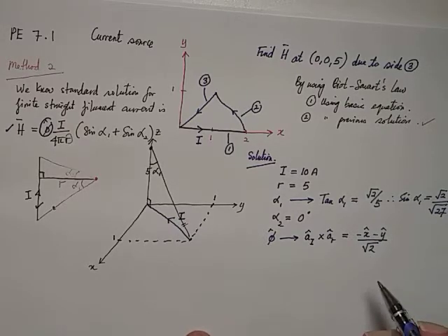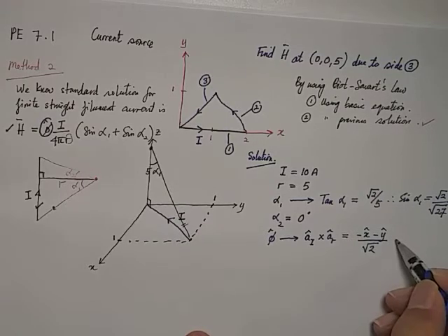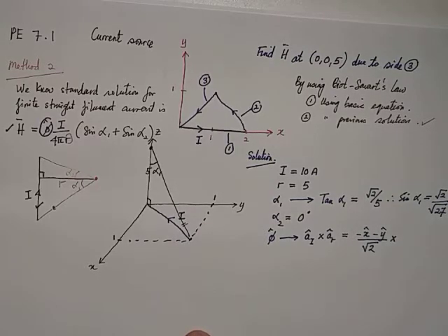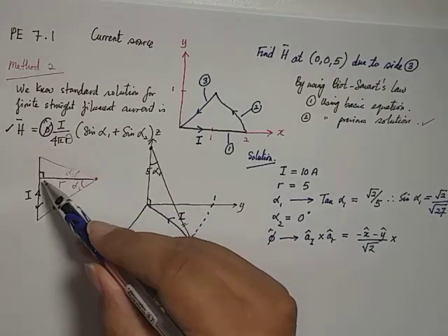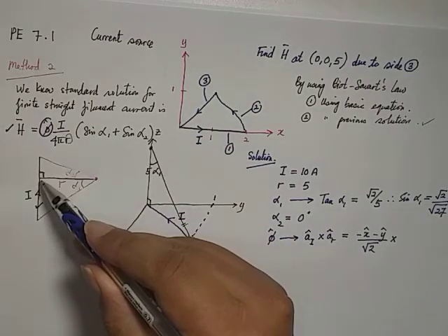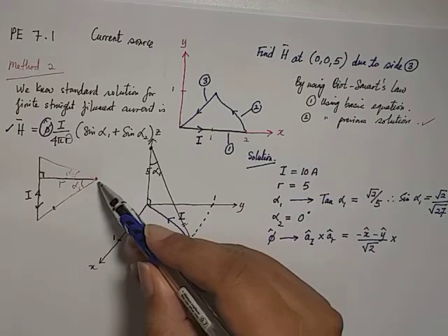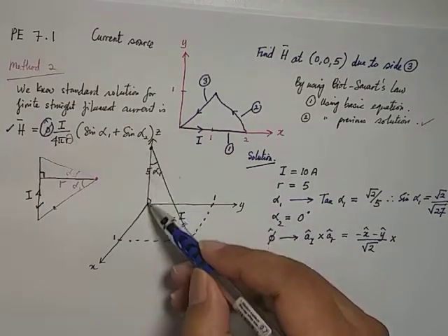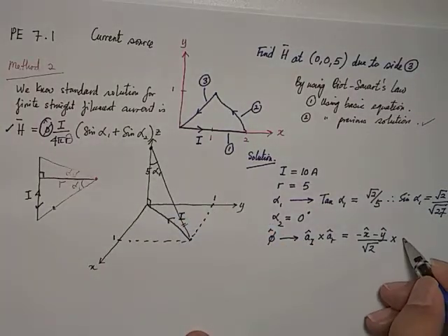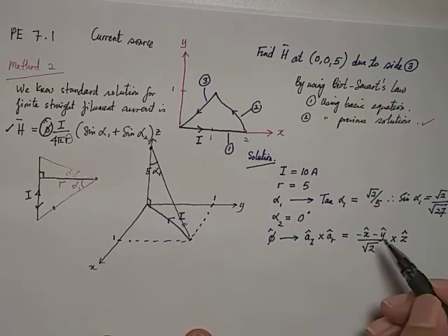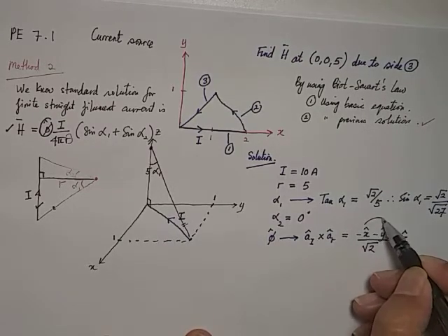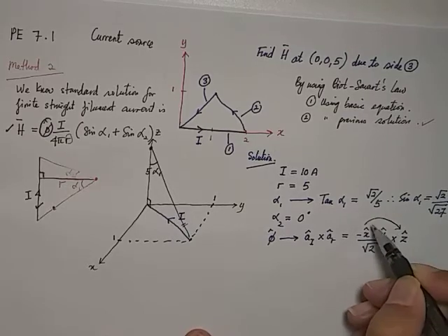So that's done already, but we have to now find what the unit vector of this line joining the source to the point of H should be. So from this diagram, we can state that the unit vector of R should be unit vector Z. Okay. So now let's do the cross product. So negative X crossed with Z will give us what?